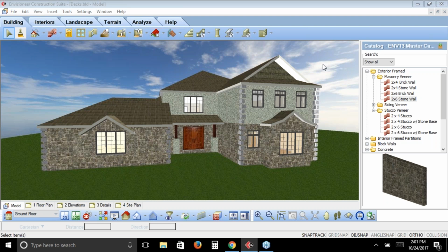When I'm putting in any kind of decks, I always recommend that you do it in a 2D view. When you're in a 2D view, you have the precision of picking the exact points where you want to put them. When you're in a 3D view, you've got the depth perception that you're dealing with. Am I picking to the outside face of the wall and picking the correct points? So I always suggest, especially when you're laying something out, to do it in 2D.